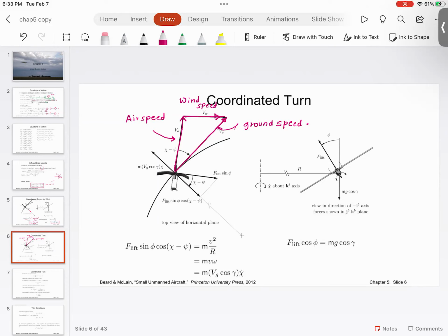That is called the pitot static tube. There are two ports: one measures the absolute pressure, and the second measures the differential pressure. There is a manometric fluid, and the difference in the manometric fluid gives an indication of how fast or slow the aircraft is going with respect to the surrounding air.